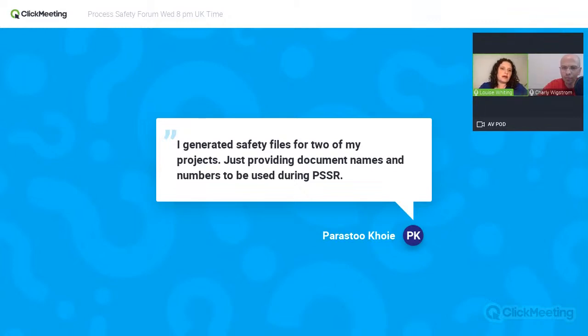You might not go into detail about how you're managing corrosion if that's not one of your key risks, but in other facilities, that might be your biggest concern. For example, if you have a lot of lagging and it's a hot, wet climate, you're going to have a real big concern with external corrosion. If you have a sour wet service, you're going to have a lot of problems with internal corrosion. So really the safety case has got to be aligned with what your key risks are in your facility. And then it will communicate what the key things are you do to manage those and where you might have identified some gaps and how you're going to close those. But it's a little bit more than just providing the list. It's like a map with some clues along the way.